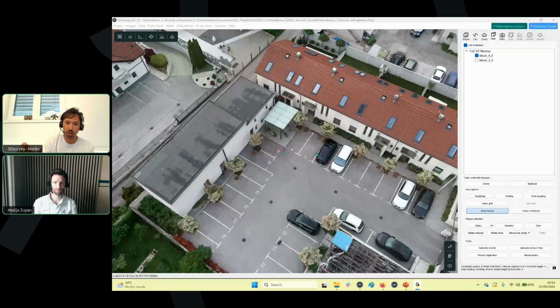turn off the propellers, grab the drone, hold it in your hand, and trigger photos manually with the drone. And you will have the same camera in the model, so the calculation is faster, calculation is easier, a lot of math is behind, and it will just work perfectly. We did this a number of times already. So there's another trick for you.